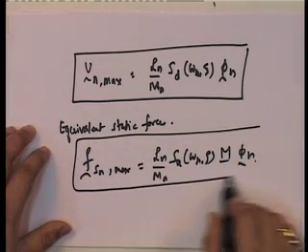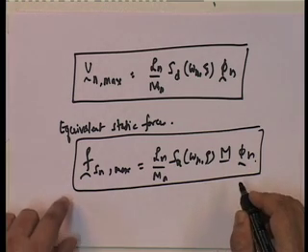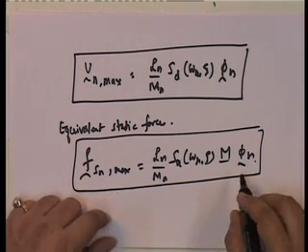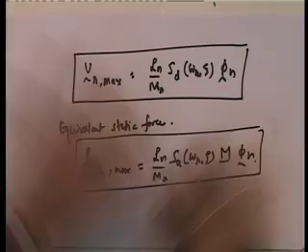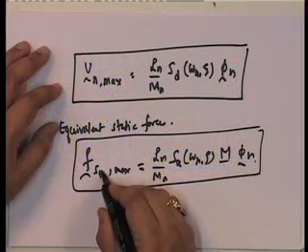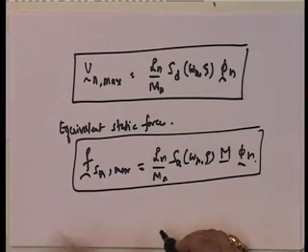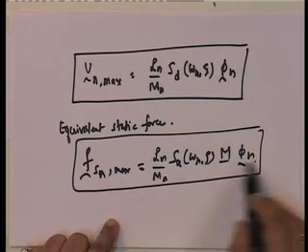These are the equivalent static forces, and you can actually apply these loads on the structure and get every other force response or displacement response or rotation, what have you. You can get all of those. Note that in the nth mode, nothing is varying with time.